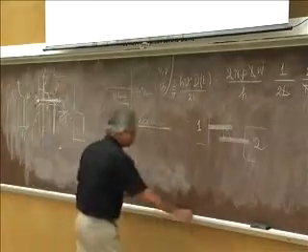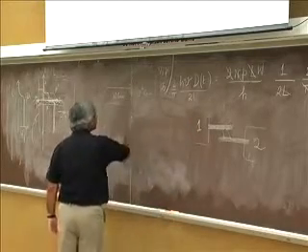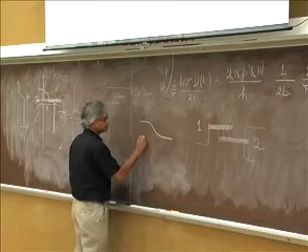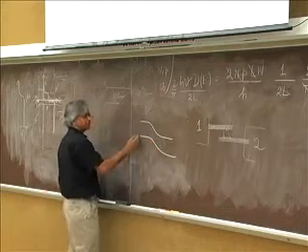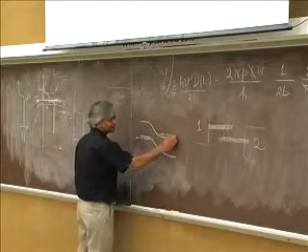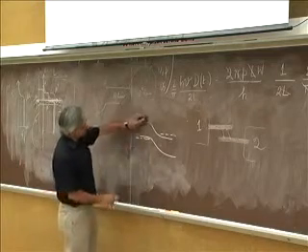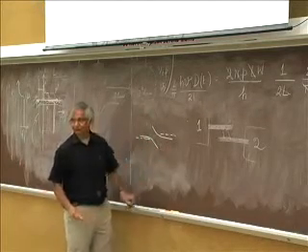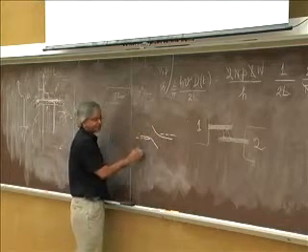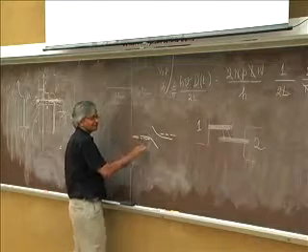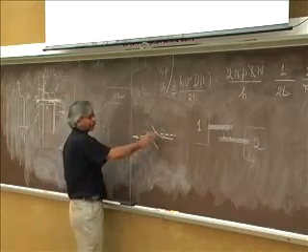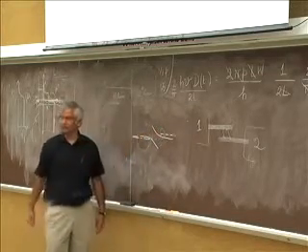Because if you draw, for those who are familiar with band diagrams, a PN junction, this is the picture we usually draw. This is the p-type side with its quasi-Fermi level somewhere here. This is the N side. And if you ignore these things, which are not very important here, that's a little bit like what I drew there: this density of states is filled from this contact, this density of states is filled from that contact, and the current flows because of recombination processes that take you from one to the other.